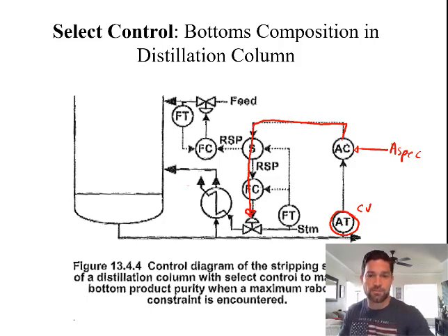Okay, but we're not doing just feedback control. We also have things set up such that the composition controller is cascaded to the flow of steam. So we have a cascade control on the steam. We measure the steam flow and we have a flow controller. The composition controller is now cascaded to the flow of steam, which controls the valve position on the steam flow. This cascade system accounts for disturbances in the steam pressure that might affect the flow without anything changing in the feedback control loop.